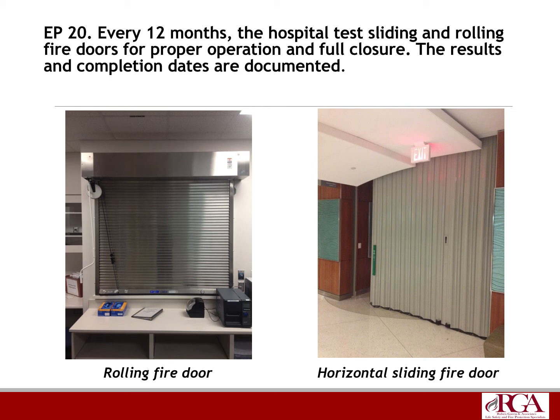They're simply checking that the fire alarm interface is doing what it's supposed to, and that is to simply release these devices. So I know that doesn't constitute your formal NFPA 80 inspection, but it is important that they check to make sure that these are dropping out because they are integrated into the fire alarm system. So there's kind of two checks there.